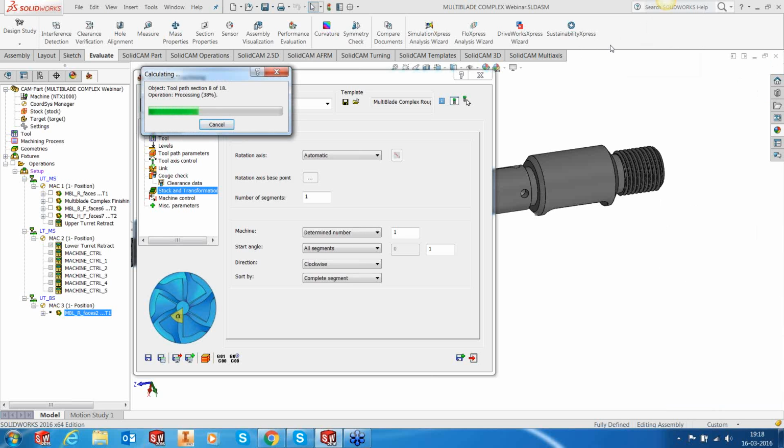Okay, so it does only impellers, blisks, and parts like this. We've also seen some of our customers use it for machining gears on 5-axis. So if they have a spiral gear, a spiral bevel gear, they use the multi-blade, because the gears basically have, if you look at the geometry perspective, not the shape, but the geometry perspective, something similar to blades.